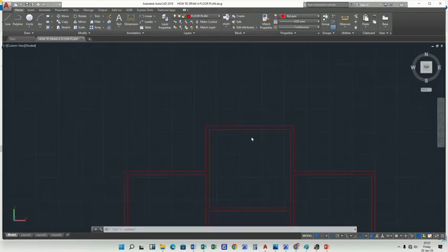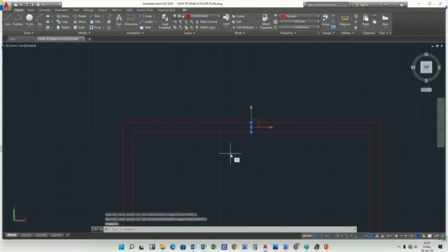I pause the video for fast forward so that I don't waste much of your time and your bundle in downloading this video and watching it. So I'm drawing now insertion of openings on the wall. I've drawn a polyline there to cut the wall. Then I've said offset 600. I click on the right and on the left respectively.